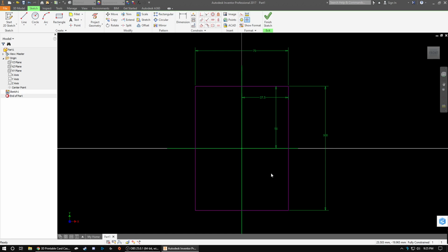When you start making other sketches on top of sketches and sketches on sides of parts and all that other stuff, it's really important to make your sketches fully constrained, because then when you go and change dimensions later on, those other sketches that you've built off of sides of parts and all that will move with it and accommodate for that. If you don't, things can get a little bit messy, and it doesn't allow you the flexibility of altering your parts willy-nilly, right? And we can get more into that later.